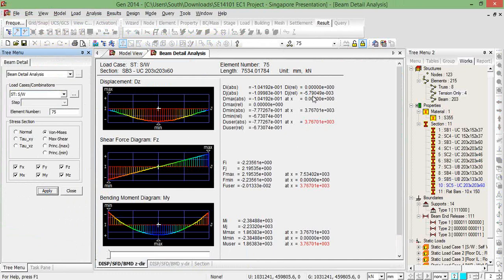You might be experiencing axial loads coming through the beams. You've got brace members coming down, being supported on beams. So we had to make sure that the location wasn't at a vital point within the section for us to then put a break in.